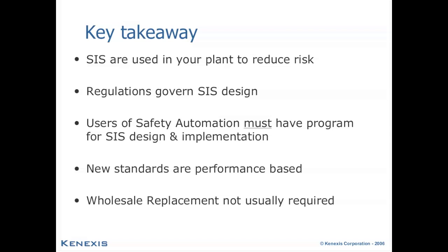There are various regulations that govern the safety instrumented system design. Here in the U.S., those are the Process Safety Management Standards by OSHA and the equivalent standards by the U.S. EPA. There are maybe one or more local standards or other good practice standards, such as the NFPA, that come into play for specific SIS applications such as fired equipment.